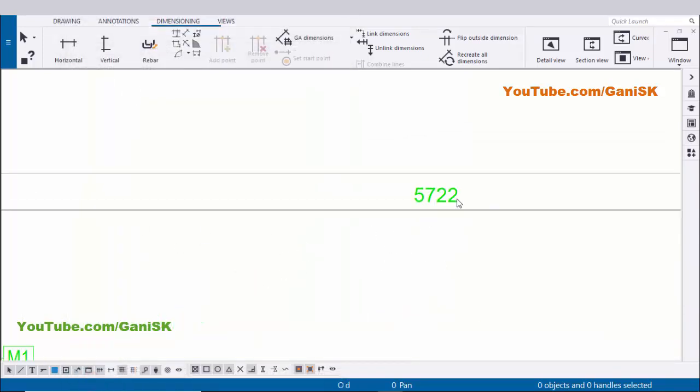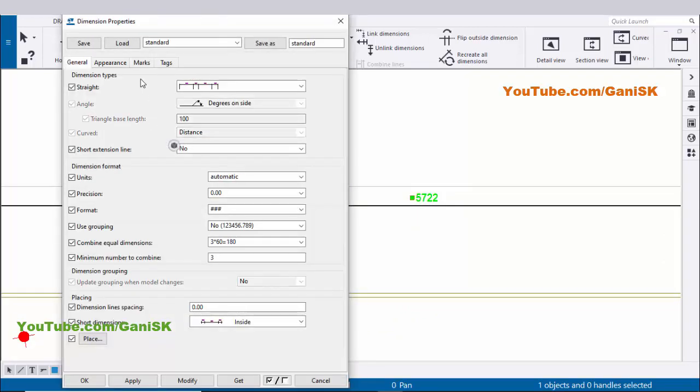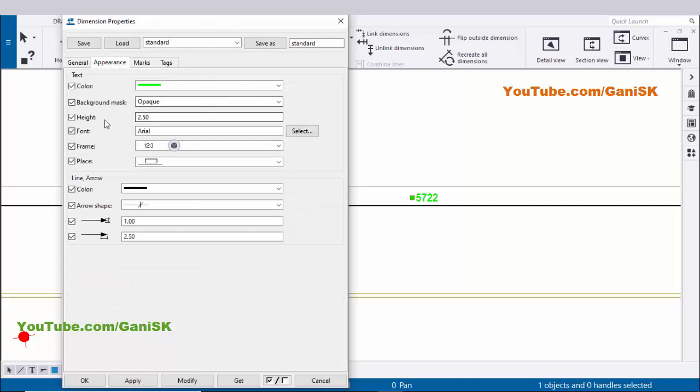If you want to change this text height in the dimension, double click on it. Now you can see in appearance we have the height 2.5. If you want to increase it, you can increase, and reduce, you can reduce it. Okay, click on modify, apply, OK.